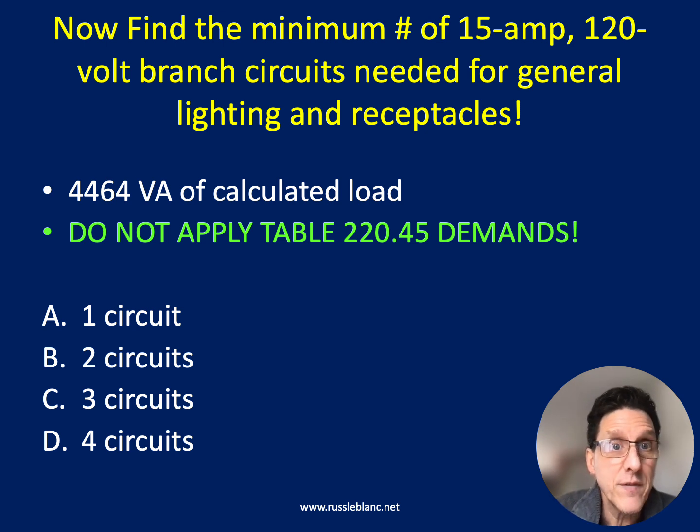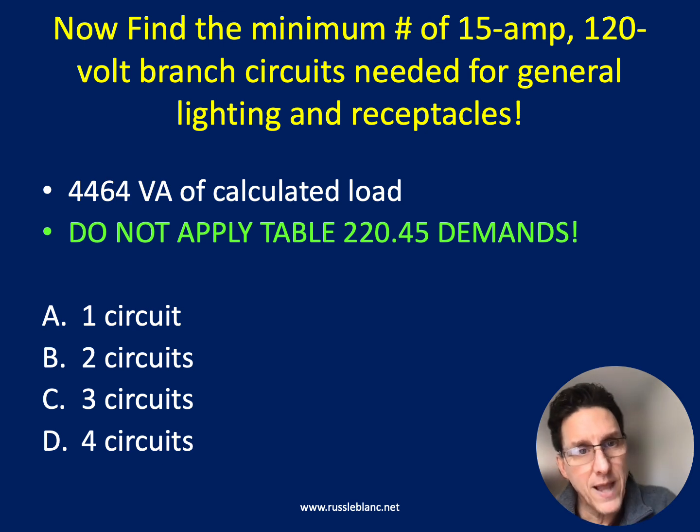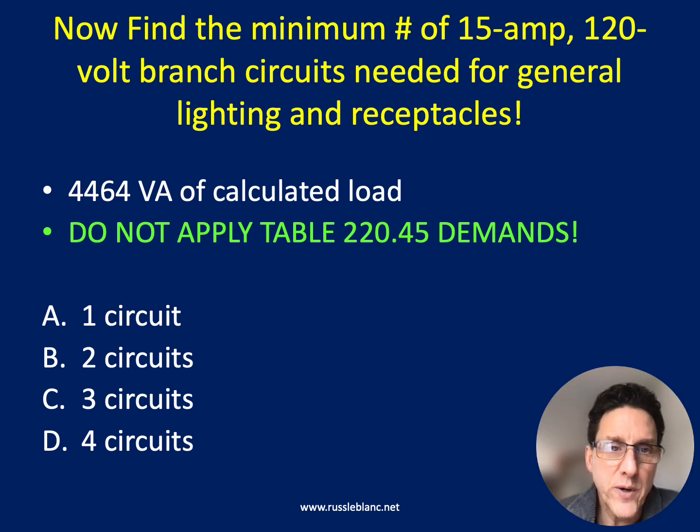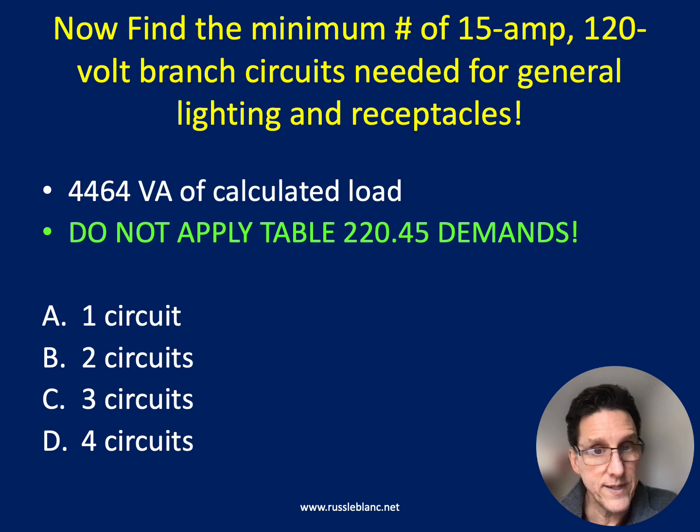I will have another video where we will use that table. We'll calculate the branch circuit lighting load, and then we'll apply the demands from table 220.45, but that's when we're calculating services and feeders. We're not doing that here. We're just calculating branch circuit load and how many branch circuits we need.